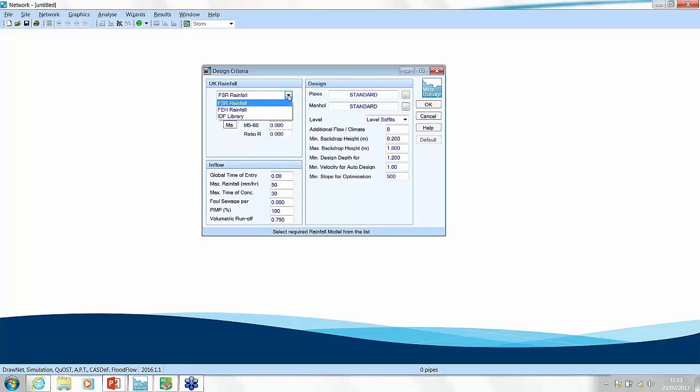So some local authorities will say that you have to pick the worst one. Others will say that you simply go with the later, the FEH-based storms. So it's a choice and it's a discussion, and it's something that should be assessed on an individual project-by-project basis.